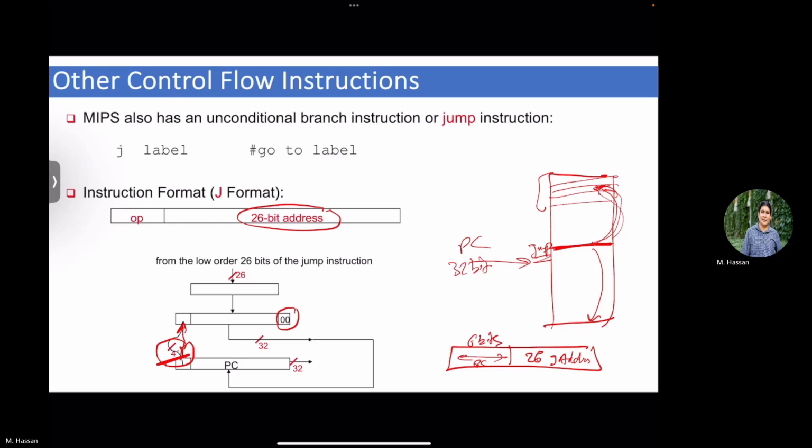If you look at the figure, that's exactly what's happening here. There are 2 bits at the beginning, and the 4 most significant bits come from the program counter. Now you format them and then you load them into the program counter. Makes sense? So I took the 26 bits, shifted by 2, because my granularity is 4 bytes, added 4 bits from the program counter, and then updated the program counter. Okay? So one final note, and then maybe you can have a break for 5 minutes.